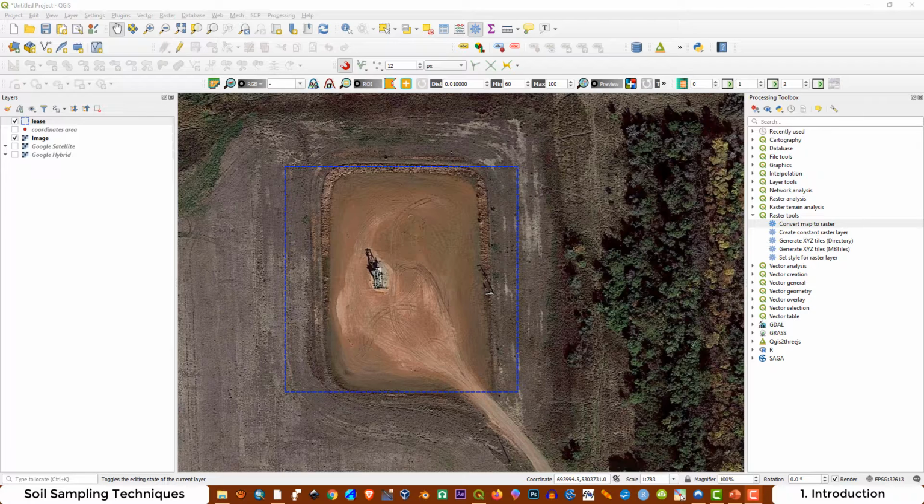At the beginning I'm going to tell you that maybe we can take one sample every 0.5 meters. I believe this distance is enough to avoid any cross-contamination between the samples. With 0.5 meters of distance, you can take a sample with a shovel, with a hand auger, and also, depending on the drilling machine, you can make a borehole every 0.5 meters. But as I said, that is the first approximation. We are going to talk more about this topic later.